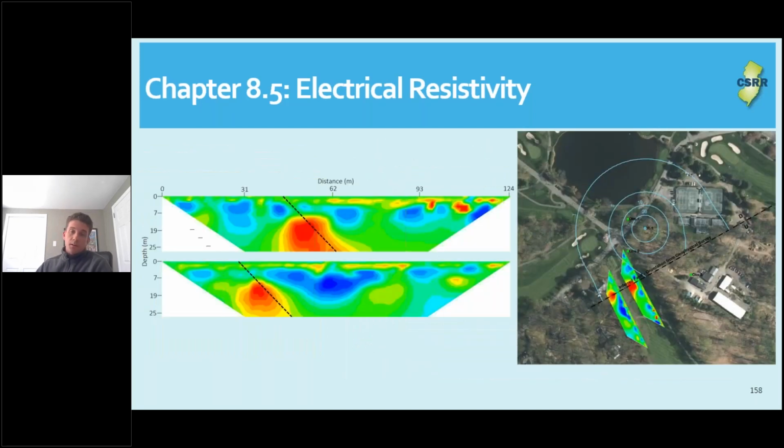So this is a project being worked on by the hydrogeology group at the survey, and they had some pump test data shown here by the blue circles. And that pump test data didn't particularly agree with the groundwater model they had constructed for the site. Nothing made sense, right? So we did these 2 resistivity lines here. So these are typical resistivity profiles. So these are, again, section view. So these are going into the ground.